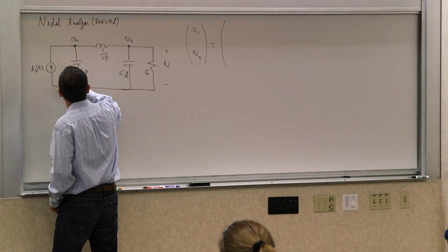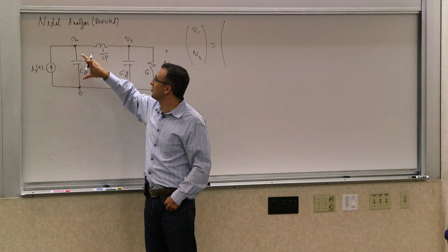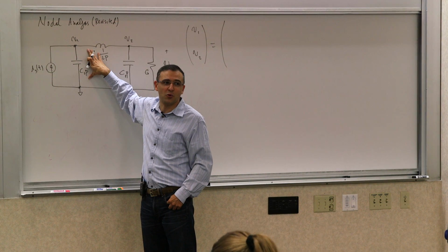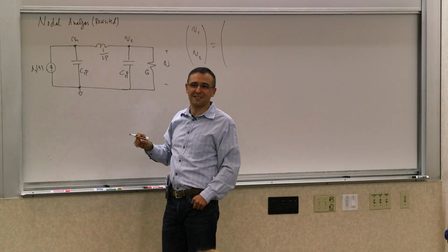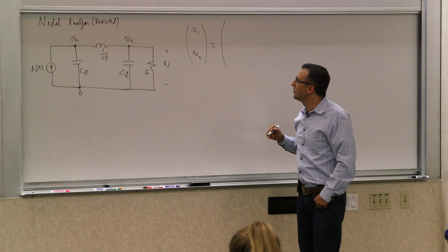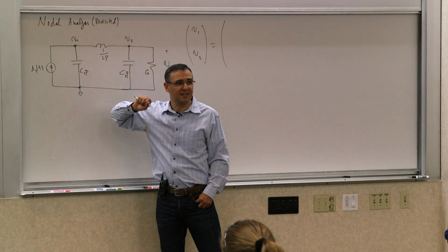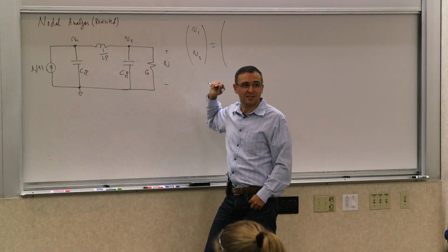Obviously, it can be a voltage too, but then the problem becomes trivial, because then you know this voltage. It's a one-node Y matrix analysis, which is a single calculation. So now that we've corrected my mistake, what are the conductances attached to it?